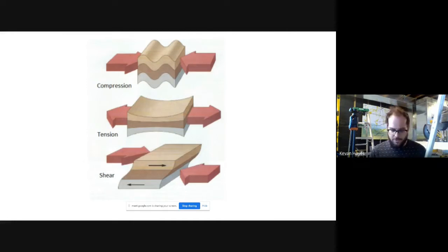So that's like when a bridge falls down, then it's experiencing structural failure. It's not supposed to fall down. For a bridge to work well, it needs to keep being a bridge. The way that structures withstand these forces inside of themselves is in these different ways: compression, tension, and shear. Some parts of a structure end up getting squished together, some parts might end up being pulled apart, and some parts might try to move side to side. We call these compression, tension, and shear.